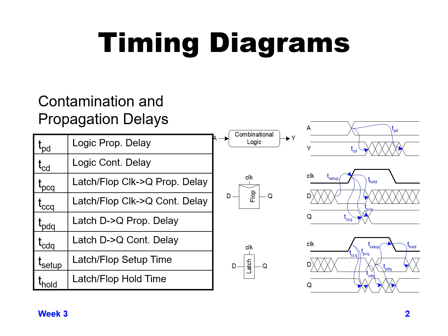So there's a setup time, which is the last time at which data can switch before clock goes low, and so the amount of time that you have to hold your data steady before the clock goes low is your setup time, and the amount of time that you have to hold it after the clock goes low, because if you try switching the data even while you're trying to close the latch, maybe a little bit after, you still could get that data value going through. So there's a T hold time that you have to hold your data stable until after the latch is fully closed.